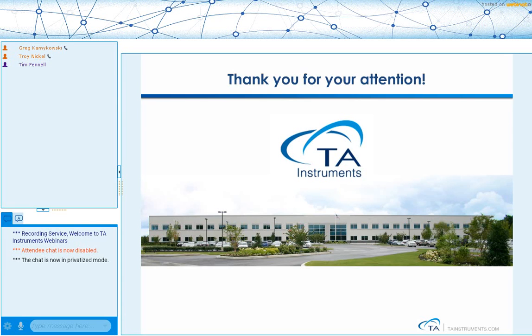Yeah, absolutely. And the thing is, foams could be varied. They could be soft foams, they could be rigid foams. And I guess in general, I would think that compression can probably do a good measurement for most foams, but if they're getting very strong, you might consider something like either cantilever or three-point bend. If they're very soft, you may even convert that to tensile testing. So yeah, and everything I've mentioned right now is linear testing.